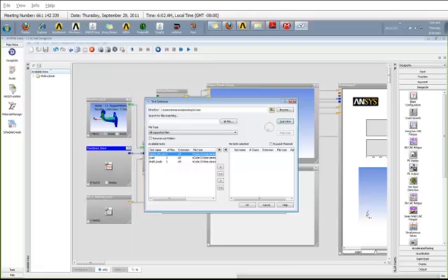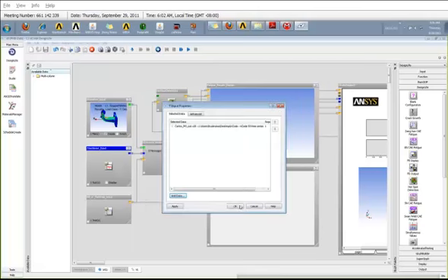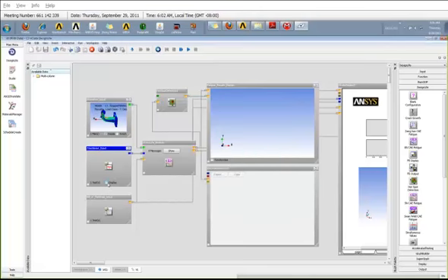You can use that one to translate those files into an S3T format, which can be read into nCode. Okay, so that's the file that I want to use. Actually, this is called Carlos TC test. It stands for Car Loading Standard Trailer Coupling Analysis. So I'm going to add that test to my time series input, and I can display my time series input.